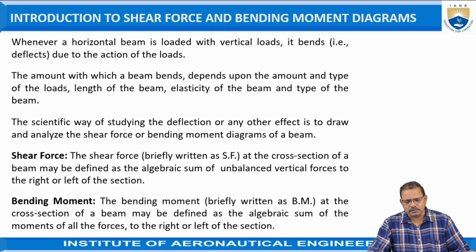The scientific way of studying the deflection or any other effect is generally done by drawing the shear force and bending moment diagrams and analyzing them. The shear force is defined as the algebraic sum of the unbalanced vertical forces acting on a beam toward the left side or right side of the section considered.